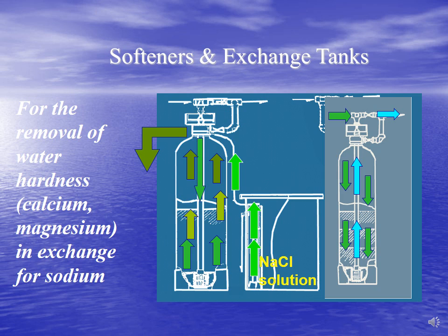What occurs at the end of each day is a process called regeneration. There is a finite capability of ion exchange in the water softener resin, so in order for the water softener to function correctly and liberate sodium, that resin has to be regenerated, meaning the sodium concentration on that resin has to be restored at the end of each day.